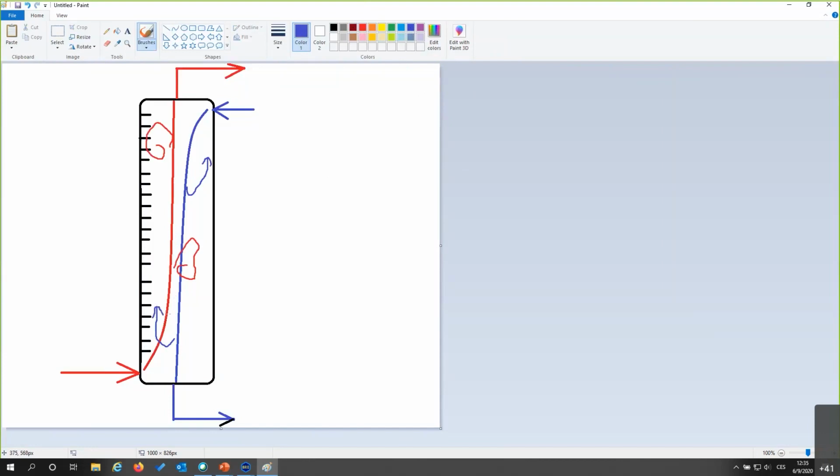So there's going to be some extent of back mixing in the column, and that's the reason why, in order to account for this back mixing, we want to take some step back from the pure countercurrent flow, and we want to use slightly larger increments. So that's how we came up with the recommendation between 0.3 and 0.6 meters.